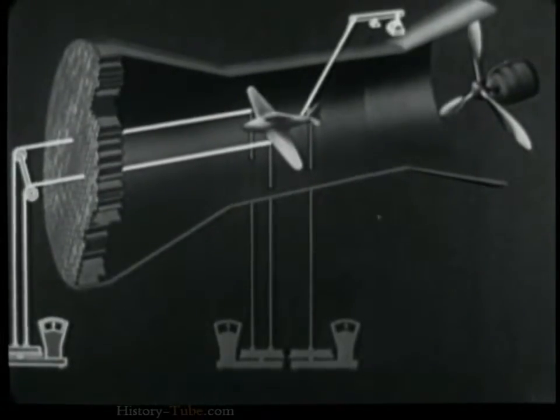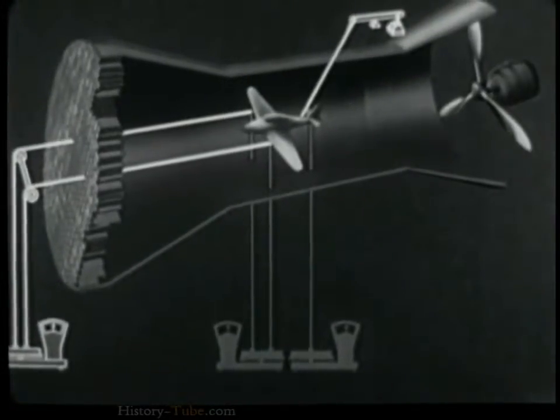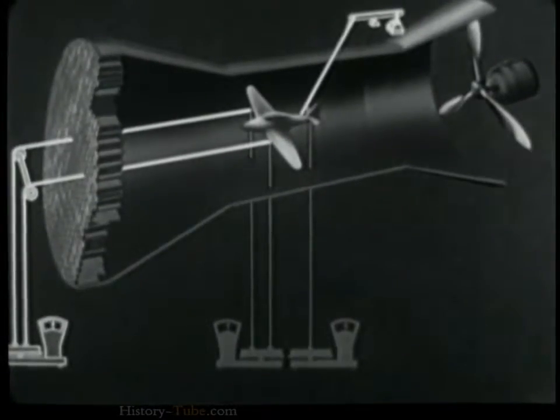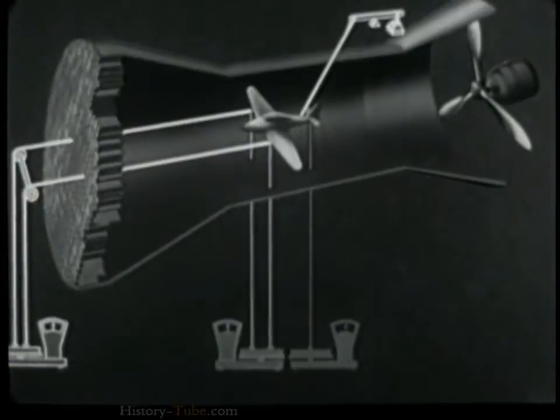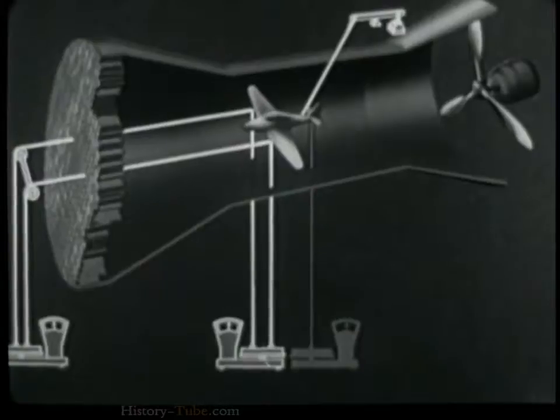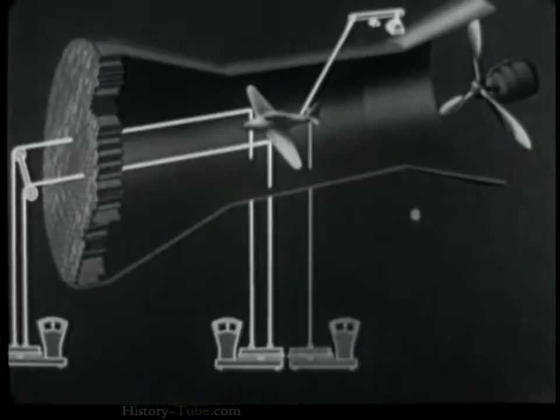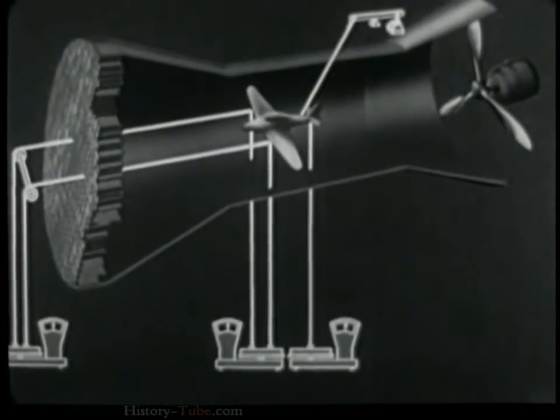From the leading edge of each wing, a wire runs forward in the direction of flight, over pulleys, and down to a bar on a platform type of scale. A second pair of wires runs vertically downward from the wings to another scale. Finally, a wire extends from the tail down to a third scale. In this way, the model is suspended so that the various forces exerted upon it may be measured.